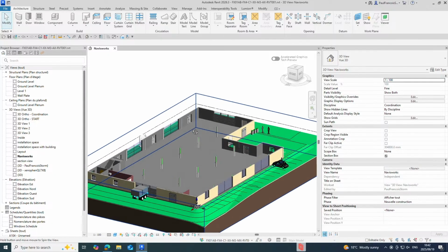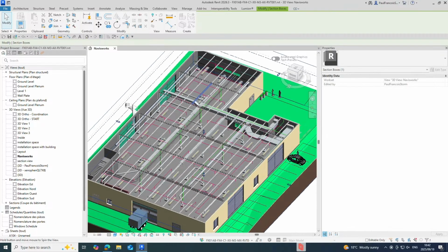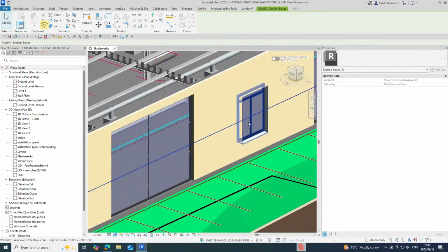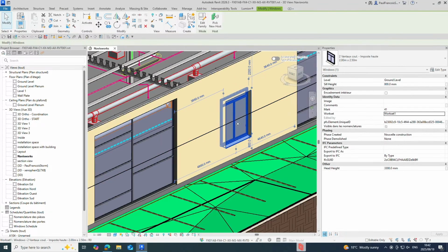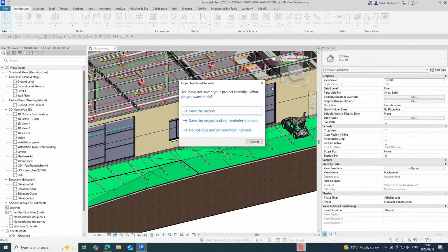This is a building that we are currently adopting at Micrographics, where we're trying to show the interoperability of software and what have you. And then inside of here, I've already done it for Windows. For instance, there's Windows. And in that window, you can see that I've created a shared instance parameter. Shared instance parameter is just Revit is a database.